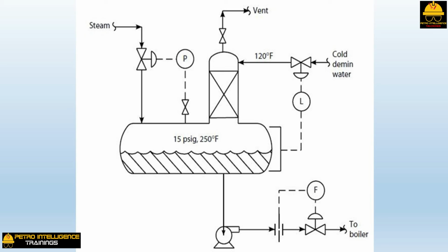Note that there is sometimes a second, hotter feed to the deaerator, in addition to the cold water feed to the stripping section. This secondary feed is steam condensate, which, having already been steamed, bypasses the stripping section. The exception to this generalization is steam condensate recovered from turbine exhaust vacuum surface condensers. Such condensate may have been in contact with air that has been drawn into the surface condenser shell and thus may have to be deaerated again. As noted above, liquid hydrocarbons must be removed by a clay polishing step to prevent oil accumulation in the deaerator, or laydown of a non-wettable film on boiler tubes.